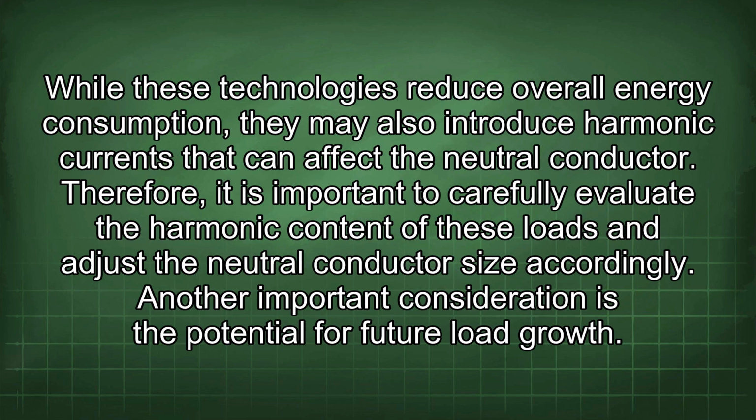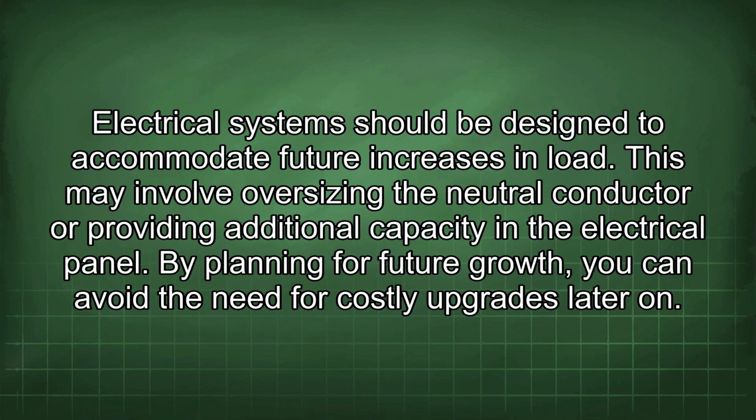Another important consideration is the potential for future load growth. Electrical systems should be designed to accommodate future increases in load. This may involve oversizing the neutral conductor or providing additional capacity in the electrical panel. By planning for future growth, you can avoid the need for costly upgrades later on.